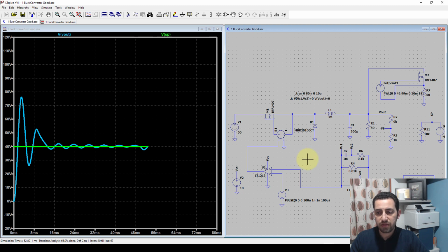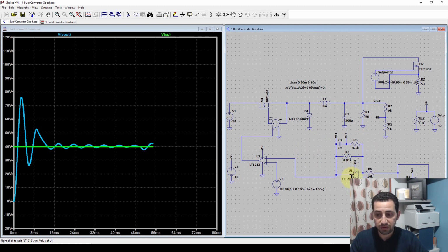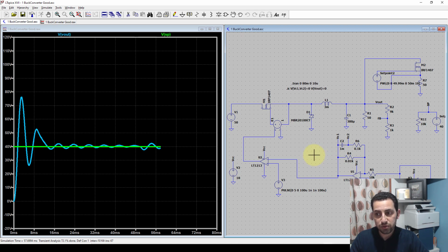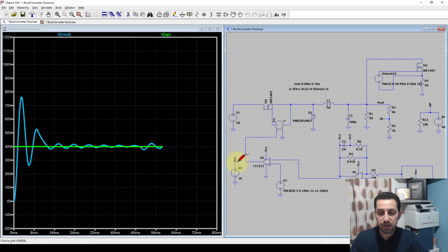Okay, so there is a third version of the buck converter and the feedback system, but using a PID controller with an operational amplifier, and there we get stuck in simulation time, and also some other details that I considered to make it work. If you look at the speed of the response, for example, we are talking about 16 to 20 milliseconds, and here after the change of the load, we suffer, so the simulation is not really fast.